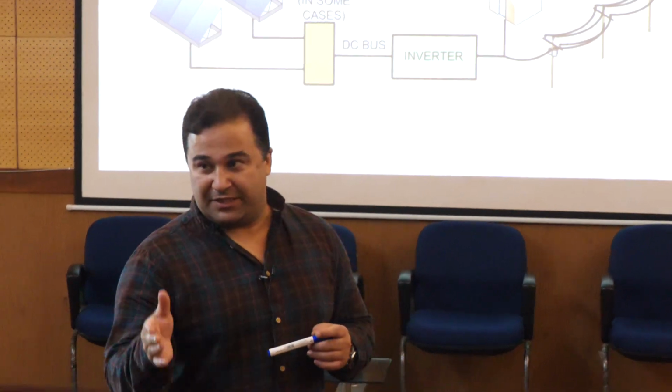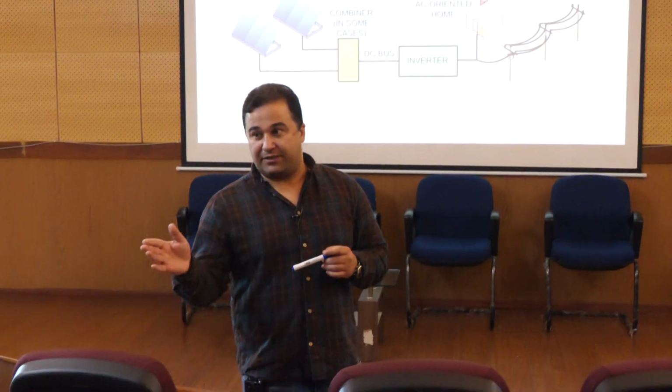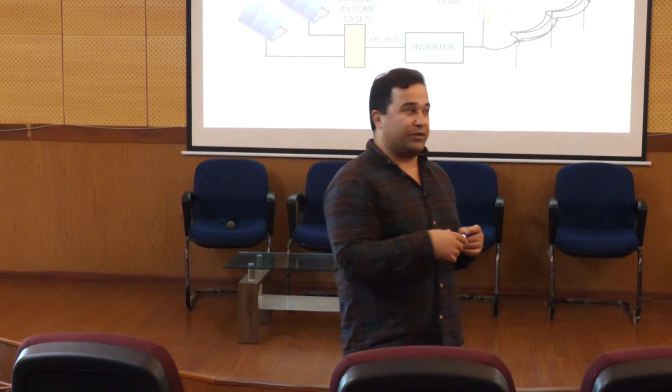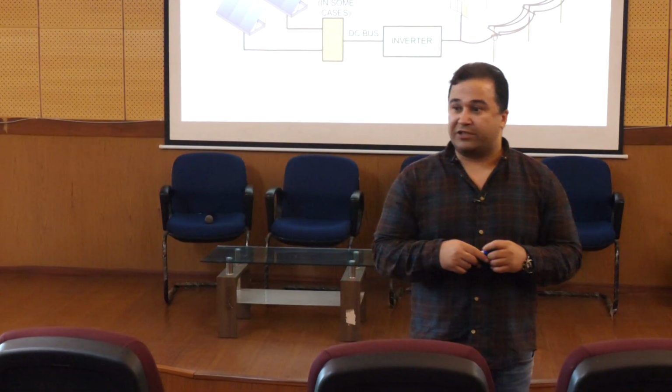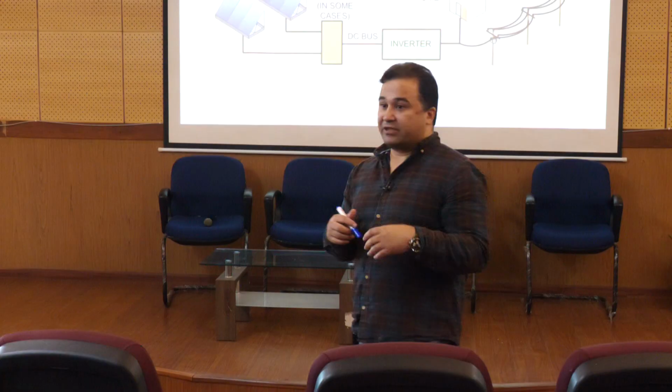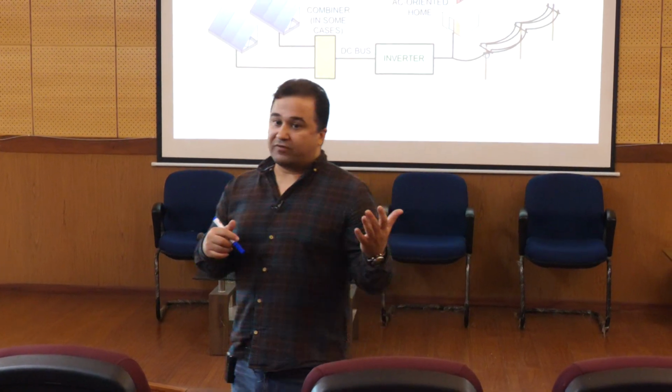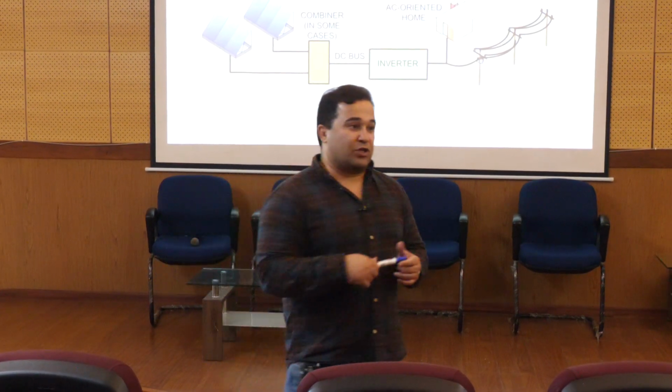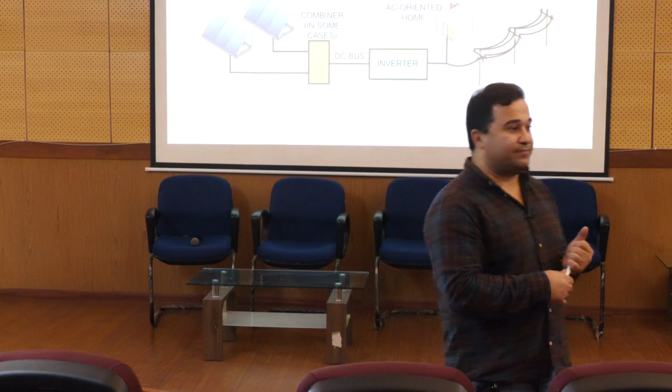DG. Why? Because we are considering both, so we cannot consider it a microgrid. Sir, a microgrid is one that we can connect or disconnect, but here we can't disconnect. If we disconnect, it would not work. Yes, if we disconnect the grid, it cannot continue. Why? Because it cannot provide the voltage reference for the converter, and the converter works like a current source, not a voltage source. So, any question so far?